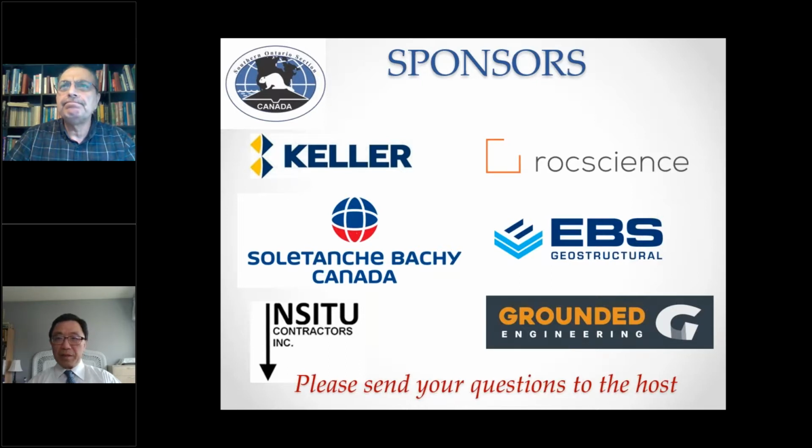So, yeah, thank you. And do you have a recommended depth between the free fall and the tremie pour? No, I said the tremie is a must. If you have fluid in the hole, the tremie is a must. If you have a dry hole, you can use the free fall. Just have enough slump.